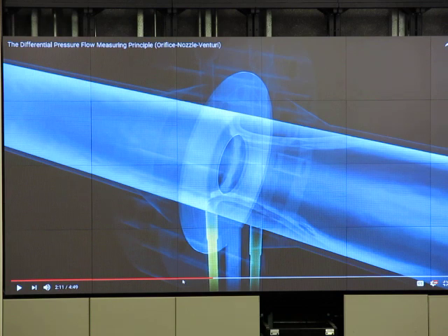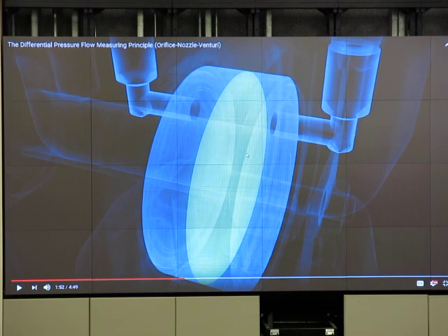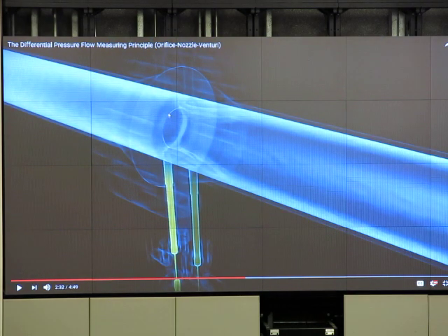The size of the orifice plate. We can have an orifice plate, we can have a nozzle. In the video it said if we have some solid particles, use a nozzle. Or if we want less pressure drop, we can use what? Venturi tube, right? So we need a measurable pressure drop, but it should not be too much. Got it? So let's say we use an orifice plate.